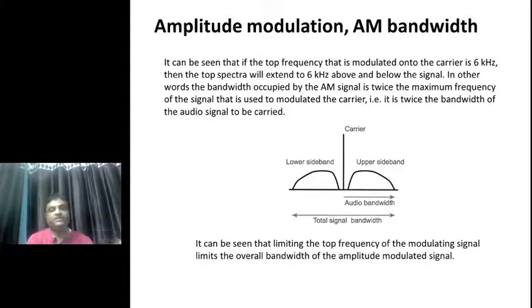Here what they try to explain is that 6 GHz is the carrier. So the upper sideband starts from 6. It means whatever the upper sideband is showing, its center is 6 GHz. Then 6 GHz is called fc. So then fc plus fm and fc minus fm. If you calculate the bandwidth, it becomes twice fm.